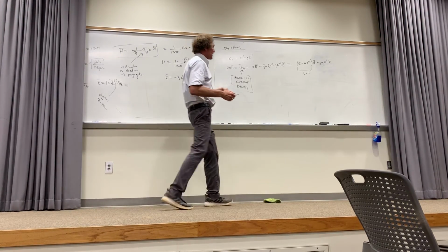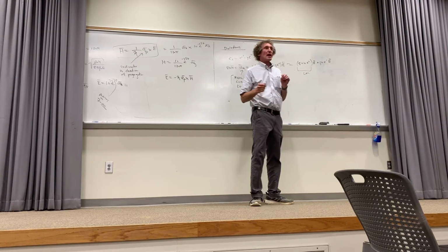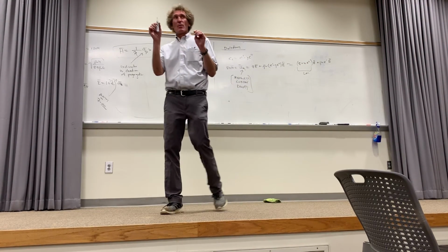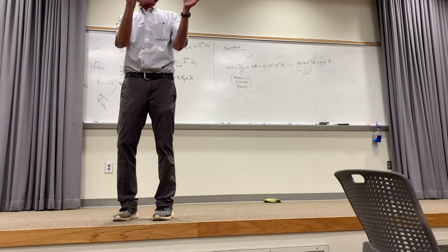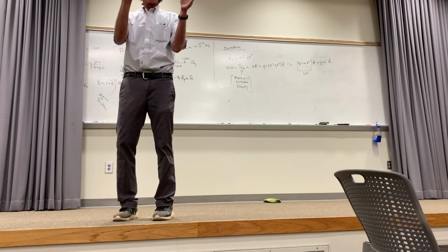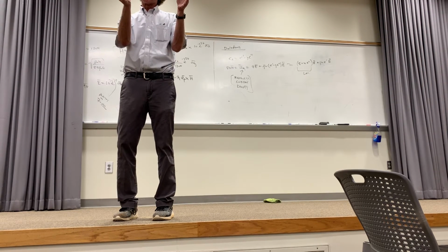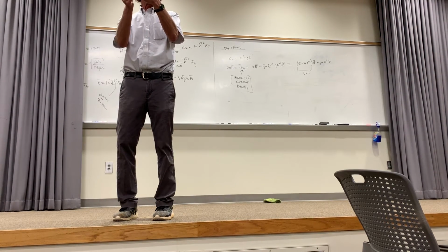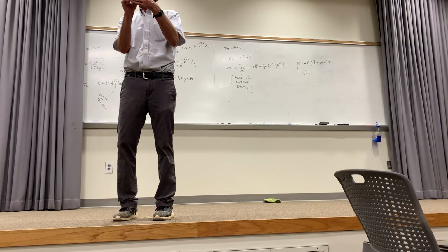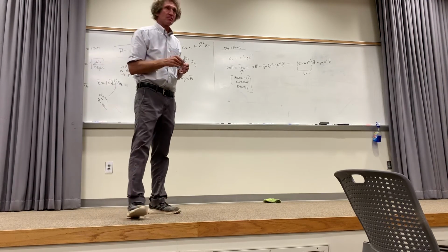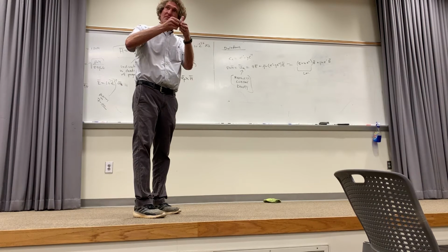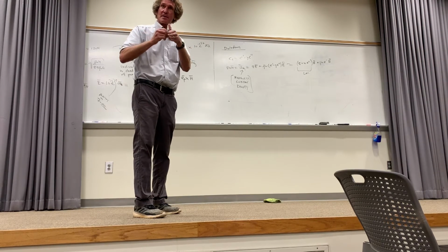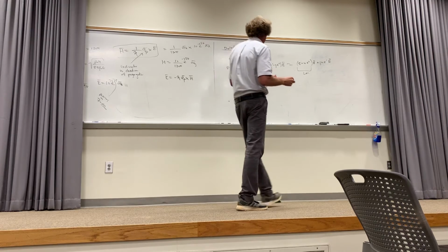When you have this term epsilon double prime, nothing flows all the way through. What happens is they're like locked in dipoles where they have a plus and a minus. And as you get a time varying field, they're wobbling. But when they wobble back and forth, they actually frictionally heat the lattice. So there's a loss, there's ohmic losses in the actual material. You follow me on that? That is related to the epsilon double prime. It's a polarization current. It's literally having things just wobble back and forth and heat up the lattice because they're doing that. That's what's going on.